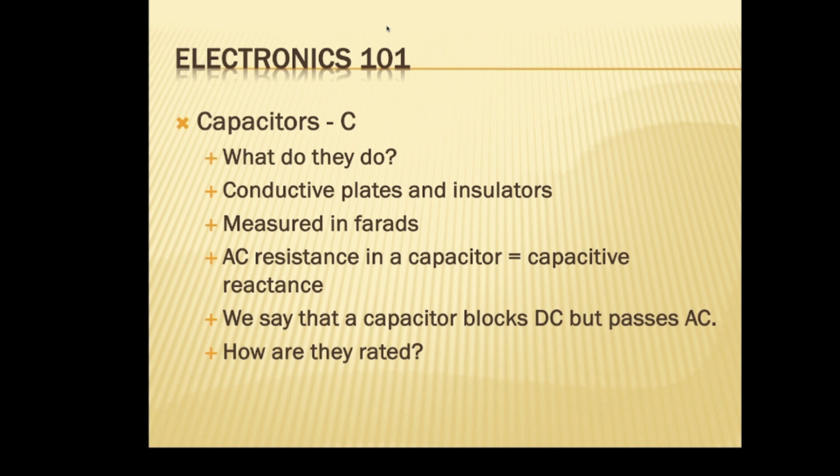0.03. Oh, come on now. 185 microfarads. See the little micro right there? Yours is auto range. I'm having a hard time holding it steady. 185 microfarads, and it's printed 180. That's pretty close.